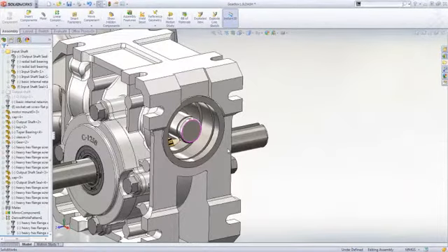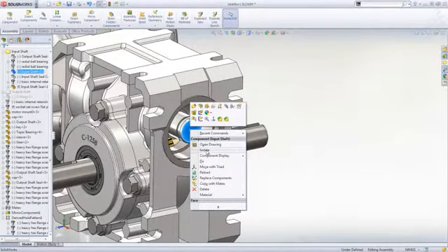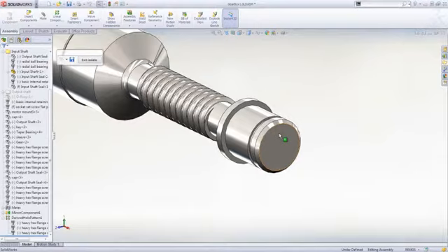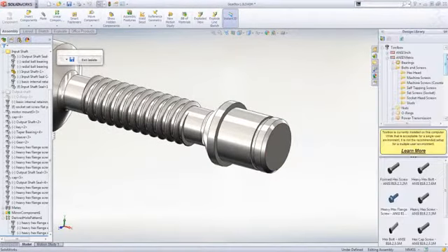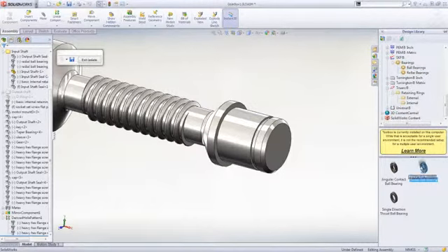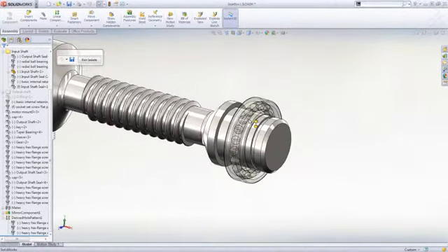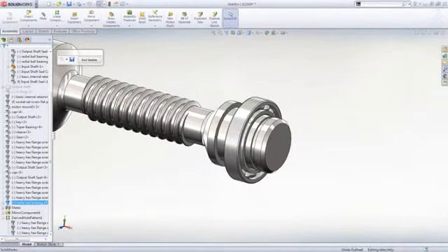Often when working with complex assemblies, it is important to dig inside of the assembly. With a press of the Tab key, any component under the cursor will be hidden, or we can use the Isolate command to select components and all others are temporarily hidden. Toolbox is not only useful for hardware items such as screws, washers, and nuts, but contains pins, bushings, keys, gears, pulleys, PEM nuts, snap rings, and bearings.